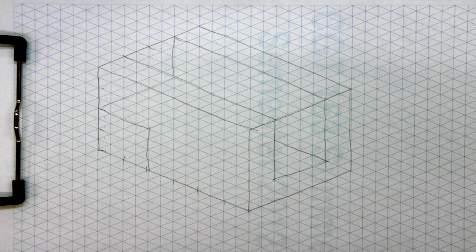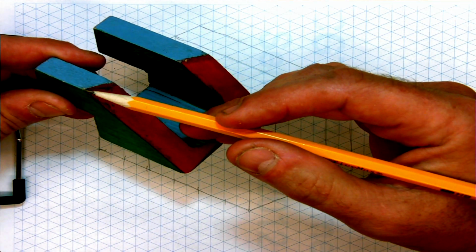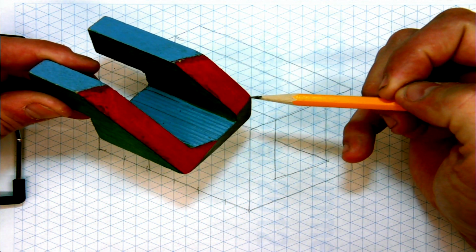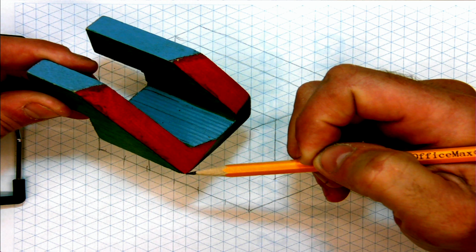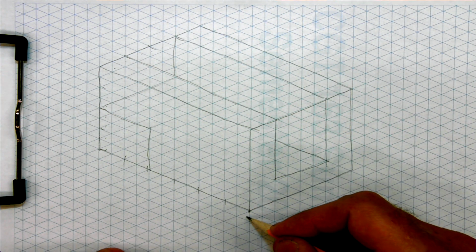Remember, when you're talking about an oblique plane, it's going to be in your 3 views. It's going to appear as a plane, and a plane, and it will not appear as any edges. So in order to do that, you have to locate the endpoints of the plane. So we have to find this point here, this point here, this point here, and this point here. Well, this one is very easy. It's the front right bottom corner. So I'm going to label that point A.